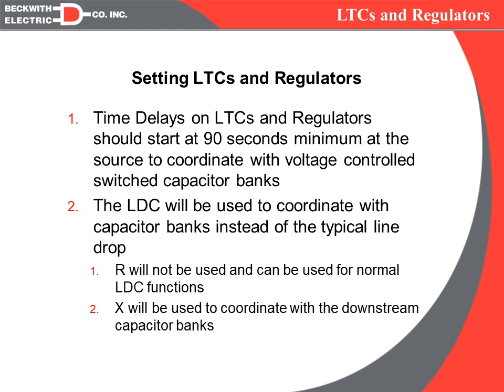And the way we're going to do that traditionally is by using the line drop setting, and especially the reactive portion. So we're not going to use the X for regular line drop. We're going to use it to coordinate with our capacitor banks. Now, we're not going to use the R for coordination with capacitor banks, so if you're using R for regular line drop compensation, you can continue to do that if you desire.